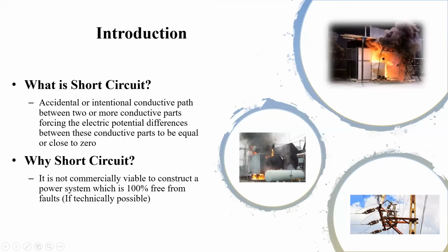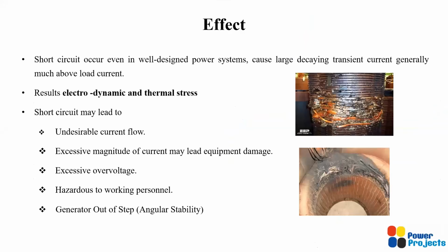Why do we need short circuit study, or why are we talking more about short circuits? In practical power systems, it's not commercially viable to construct a power system 100% free from failures. Even if somebody argues technically that is possible, it may not make commercial sense. So that's the reason why we need to study short circuit, and we need to ensure the equipment in the electrical power systems is capable of withstanding this short circuit for a short time, at least till the relay clears the fault.